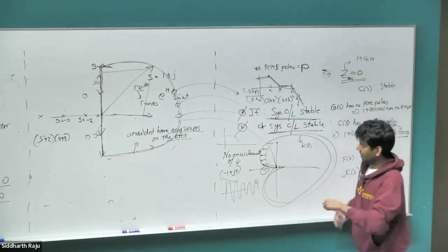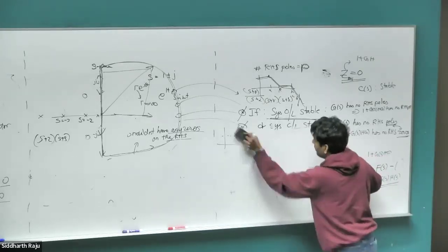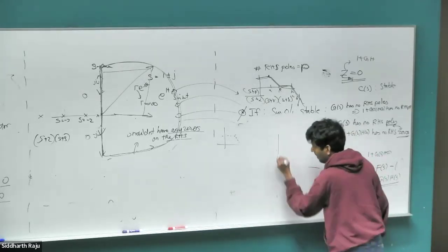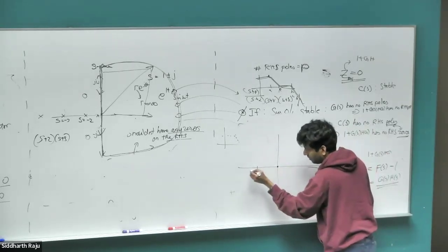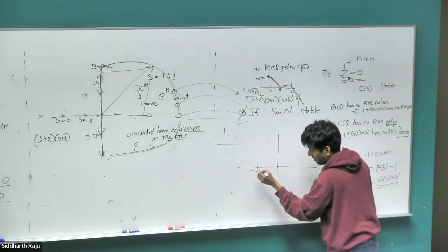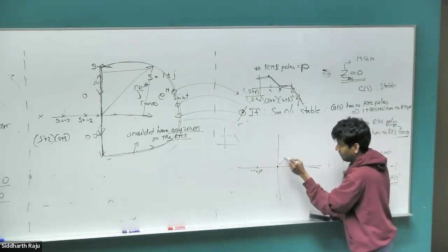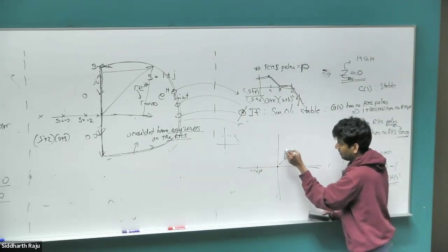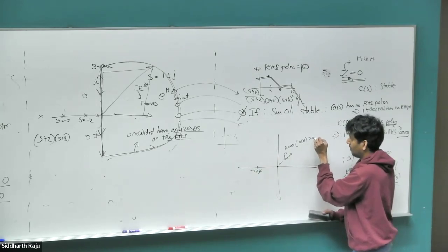Right? So all those points would just become a single point. So this is my point for stability, that is 0. All of those points map into this one, R e power j theta, with R tending to infinity, if the order of the denominator is greater than the order of the numerator.